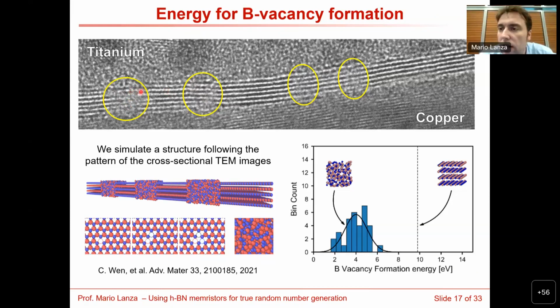They are not in a 2D lattice, but they are also located in between the layers, okay? So basically, these are interstitial atoms. This is not a boron vacancy, because if it were a boron vacancy, we would see a black line that is interrupted by a bright color and then continues. That means boron vacancy. Here, maybe we also have boron vacancies, but we definitely have atoms in the bright areas. So we have atoms that have moved.